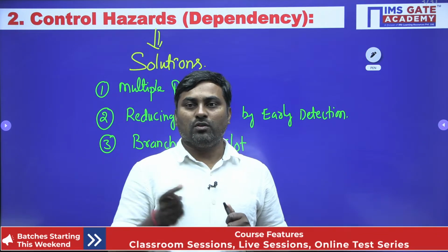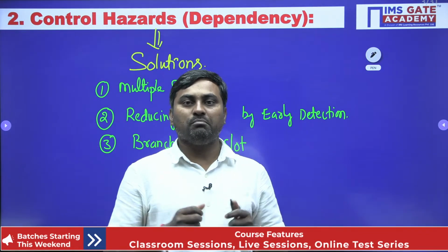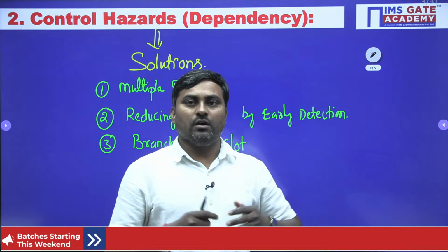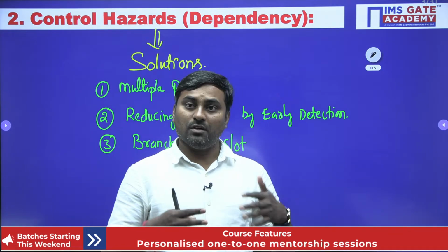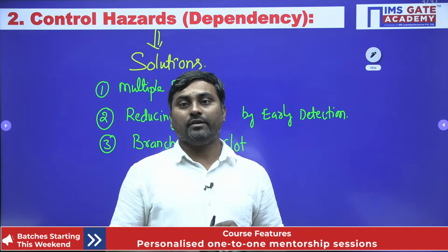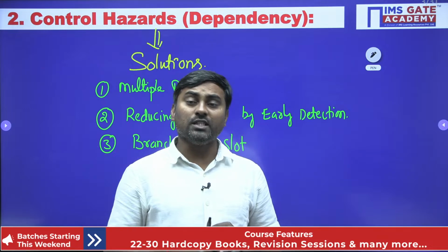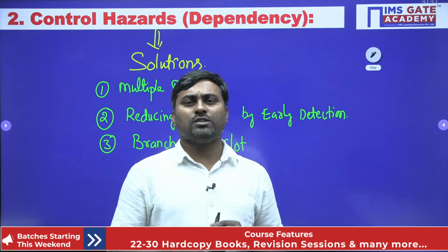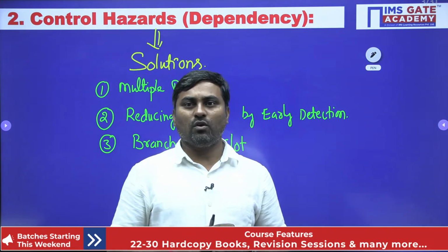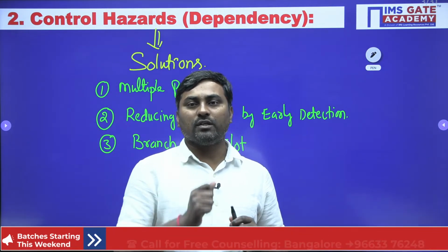We modified the decode stage to be intelligent enough to detect a branch instruction, and the generation of the target instruction also happens in the decode stage only. With this, only 1 clock is going to be wasted. How can we utilize this 1 clock?